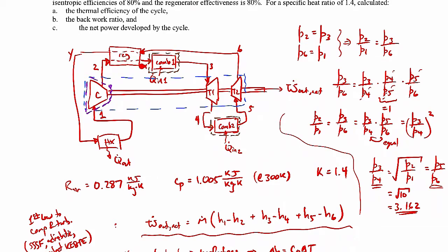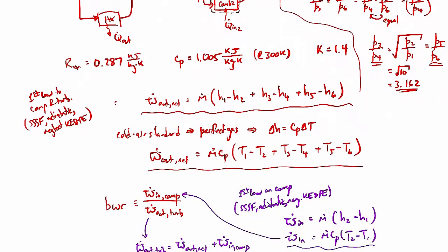So it'd be like Hx minus H2 divided by H6 minus H2. The idea here is that for 100% effectiveness, H6 and Hx would be the same. So let me write this down.